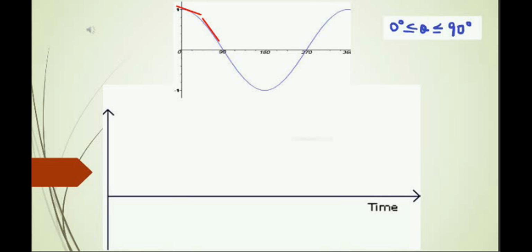However, the rate of change of steepness or gradient slows down when approaching 90 degrees. Based on the EMF formula, we have to take the negative value of the gradient as the value of EMF produced. So the values of this gradient will turn into positive figures. To reflect these values in the EMF graph, we'll draw a positive graph with a slight curve.